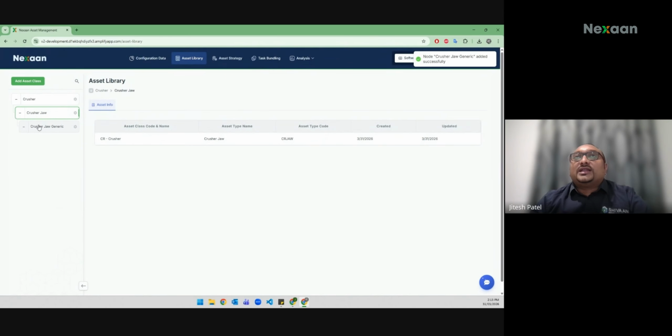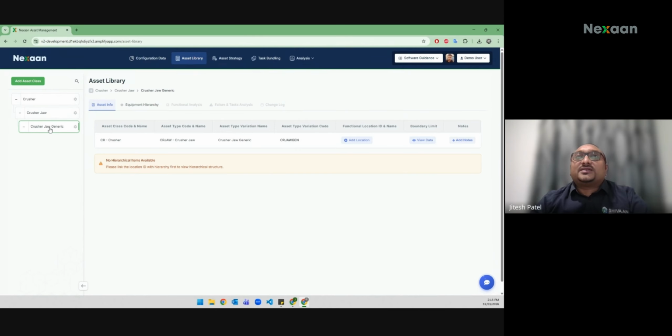Now I've got the 3 levels. The asset classification is done. You could also reference ISO 14224, but just be very careful. That's a baseline to understand how you need to build, because a lot of the things in the standards are at high level, and you must understand your business context and your assets to be able to build the asset classifications in the right way.